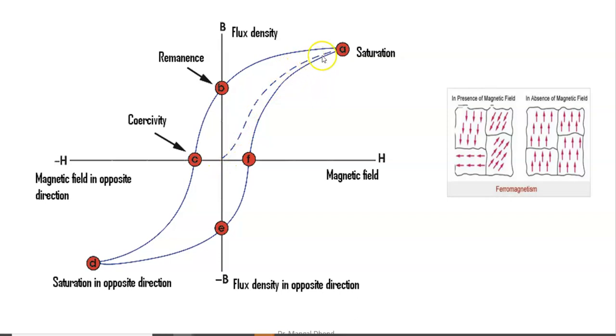Here, on this dotted curve, mark the points O and A. Draw this hysteresis loop in your notebook, O and A. And the OA part also has three different parts. The initial first part is the linear change. As H is increased, flux density changes linearly. Then it goes on changing rapidly, because as magnetizing force changes, flux density changes.